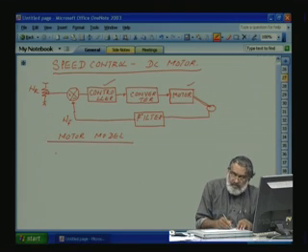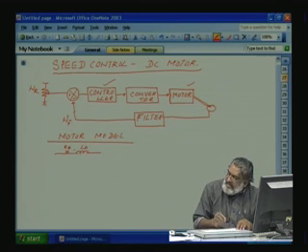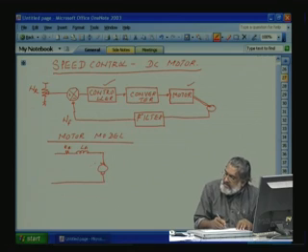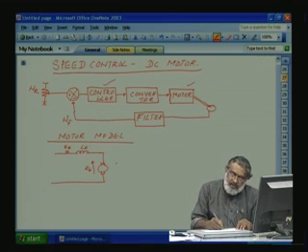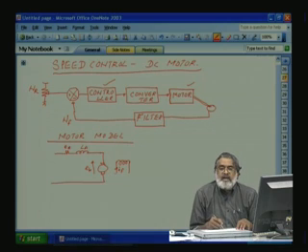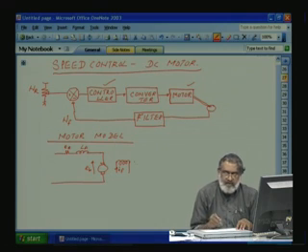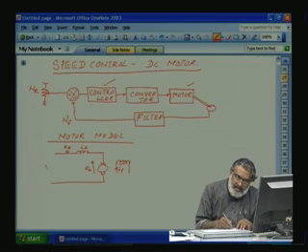So, this we can represent with the armature resistance Ra and the leakage inductance La. Then here we have the back EMF Eb. And here also is the field winding, where we are giving the rated field current, keeping it constant, and we are not disturbing that. We are only controlling the armature voltage Va. Okay. This is plus minus.